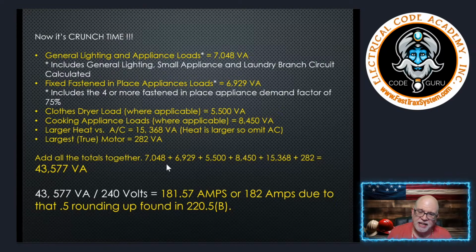But in the code, if it's a 100 through 400 amp service, a 3-wire 120/240 volt for a single family dwelling in our case, you're allowed to apply some rules that are in 310.12. And we refer to these rules as the 83% rule. Now, this is going to yield usually one size smaller than what you get in 310.16, and it's okay. In the 2023 edition, you've got a nifty little table. In the 2020, I think you do as well. Prior to that, you had to go to Informative Annex D, under the D7 example. But it's basically called the 83% rule.